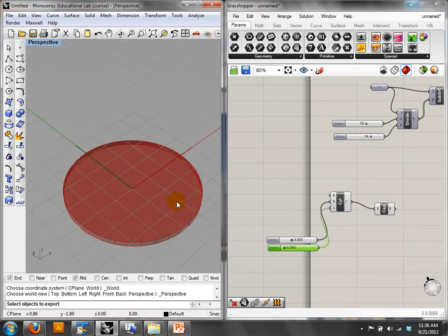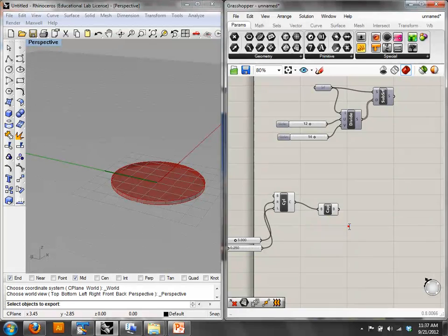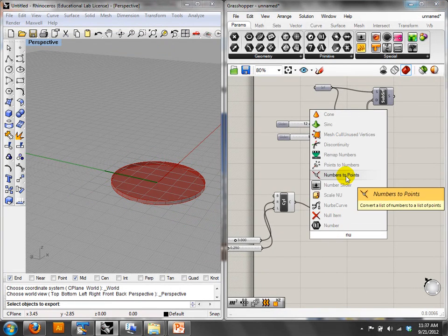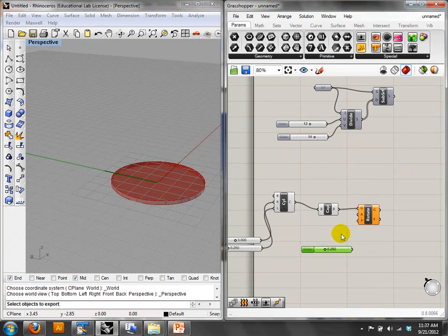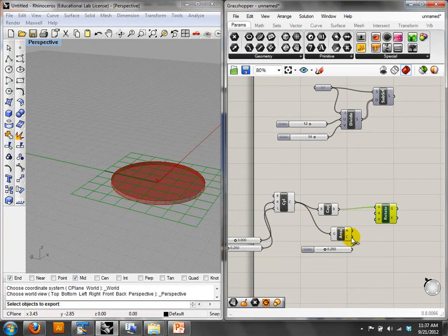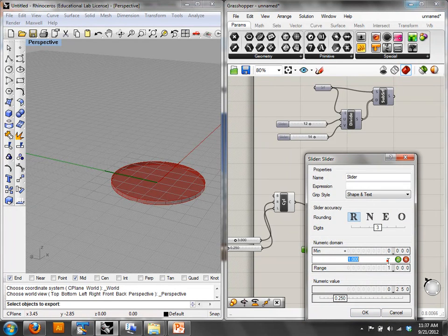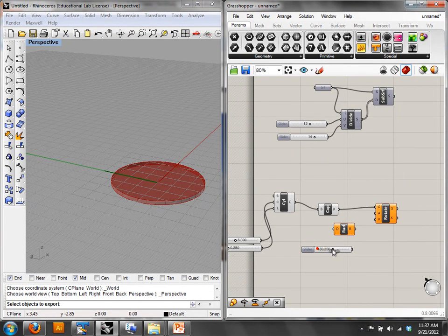And what I want to do though with these disks is I want to sort of angle them. So I'm going to go in and rotate these disks. So I take the geometry, and we have this pattern that I think we've talked about a lot of times before, where we're going to rotate them. Okay, and then do a radians component. K360. And I want this to kind of flip end over end, like you're flipping a coin or something.